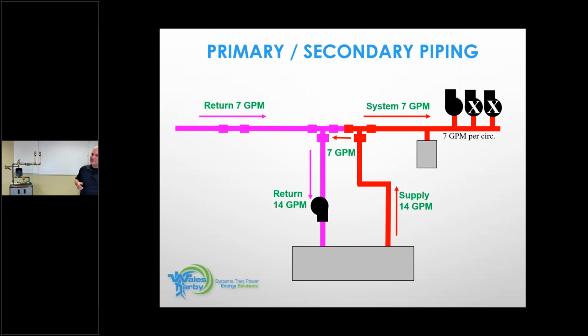So you got 2 answers coming in: ramping down, running half capacity. Right. It's going to slow down. And the reason it's slowing down, just so everybody's aware, is that most condensing boilers will have a return sensor on them. So if we're putting hot water out here, I'm not going to say a temperature, and we're coming back with a little bit cooler water, but 50% of the water going back down this return is hot water from the supply. We're mixing it. So the return sensor will see that, and it will say to the boiler, reduce your input.